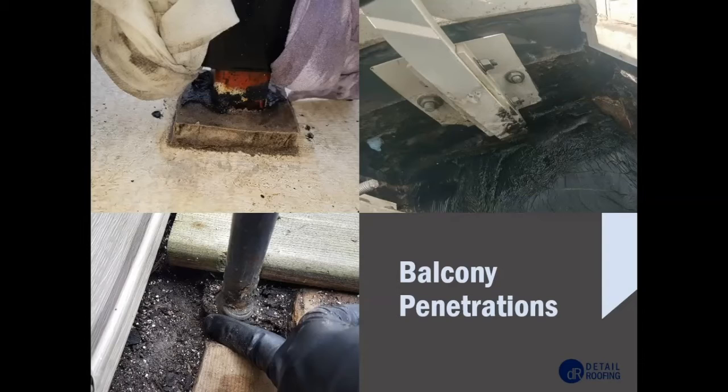This is something that you want to be monitoring and making sure that they are adequately sealed, because if they are exposed and there's any openings there, or the sealant deteriorates to the point that there's cracks in it, then these are weak points that are very common leak issues.